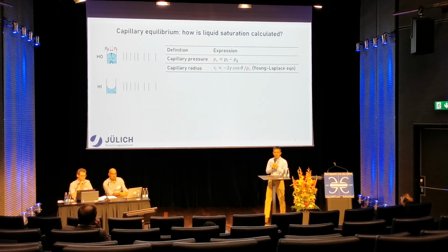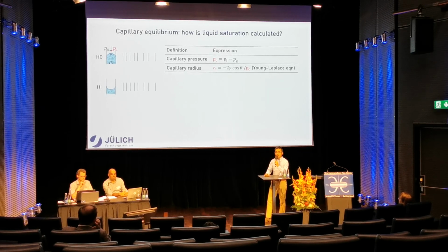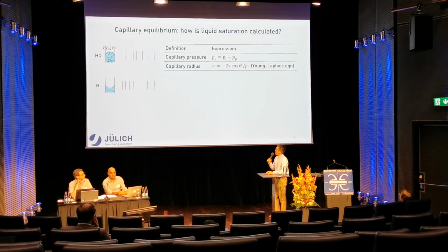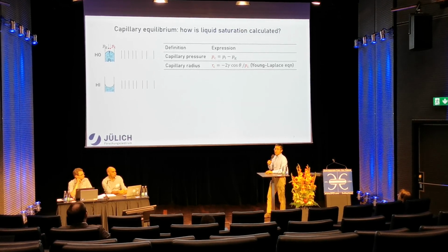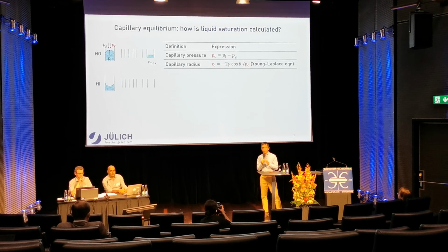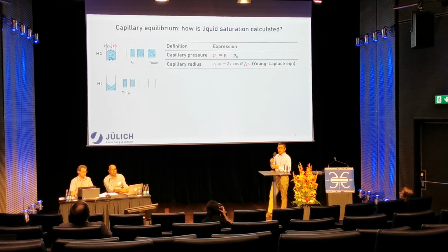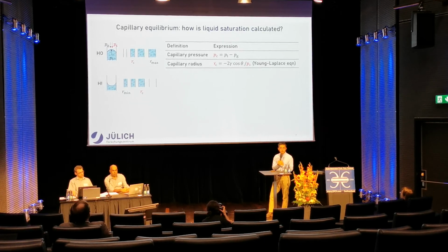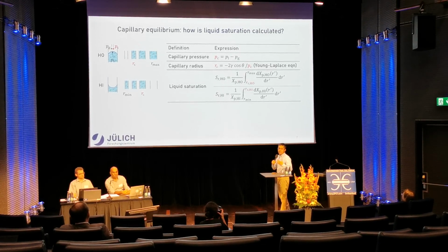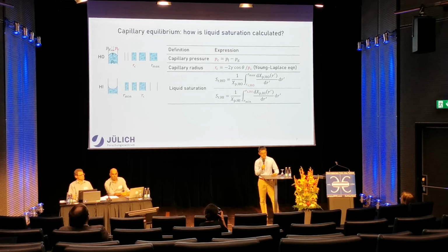The saturation is calculated by capillary equilibrium. At the gas and liquid interface, force balance is maintained. The difference between liquid pressure and gas pressure is the capillary pressure. The Laplace equation gives the capillary radius. In hydrophobic pores, all the pores larger than the capillary radius are filled with water, whereas in hydrophilic pores, all the smaller pores are filled with water. The saturation is simply an integral of the pore distribution over all the filled pores.